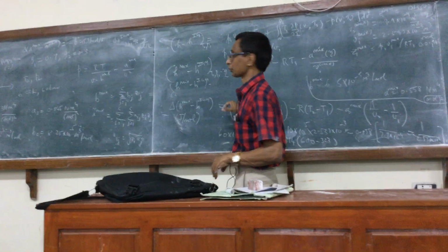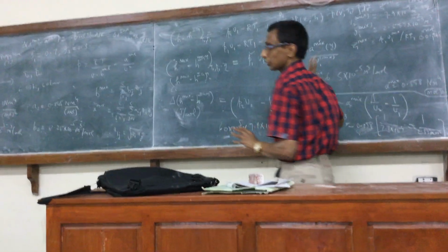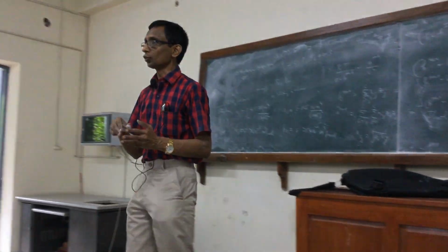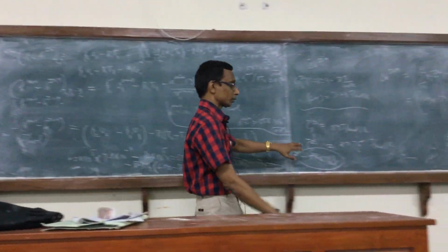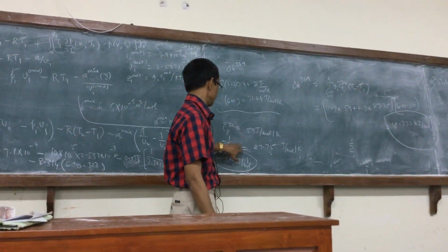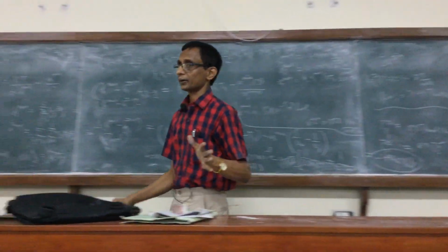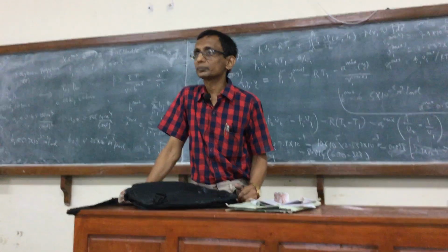We've already got the expression, right? And then calculate this. Because V1, V2 is given, you can easily do it, only substituting is required. Now for the other part, the ideal gas will obviously be log T2 by T1 and all of that. But for Cp, you can use the same average specific heats and simplify the calculation. Are there any questions?